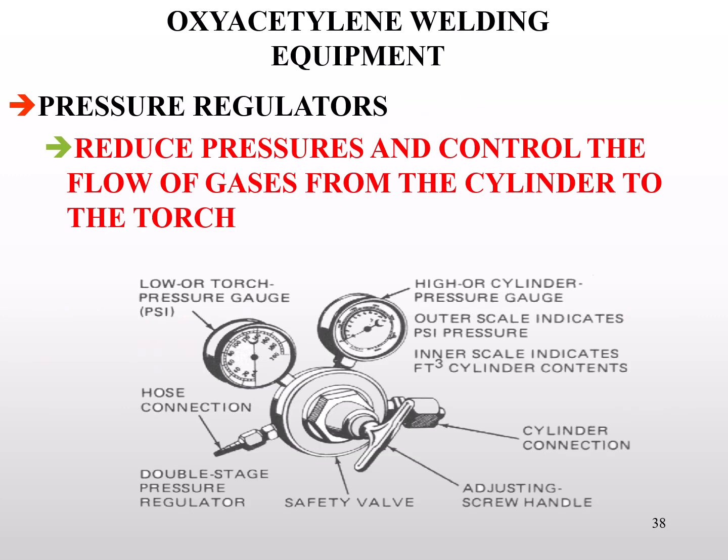Look at a piece of equipment that's very important, and there are some FAA questions involving this equipment. We have to get the high pressure gases down to a pressure that we can work with, and the way we do that is by the use of pressure regulators. In this case, this is what we would refer to as a dual stage regulator, and the way I know it's dual stage is we have two gauges visible on the regulator. Now here's a key point. The gauge nearest the bottle will give you your bottle pressure. The gauge furthest from the bottle and closest to your torch connection reads our working pressure.